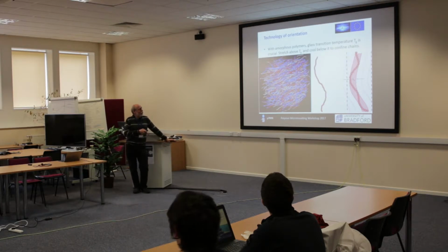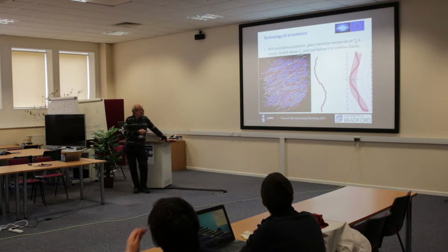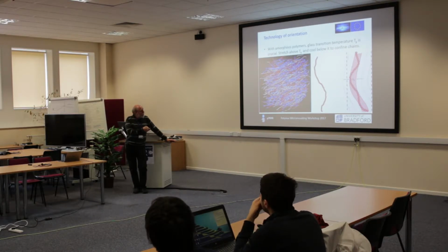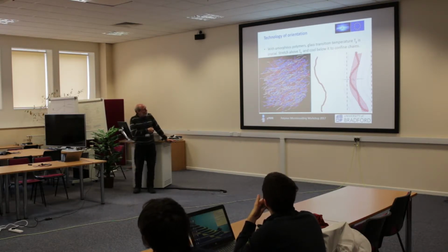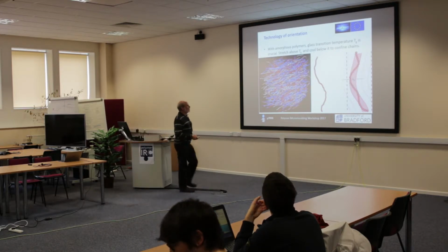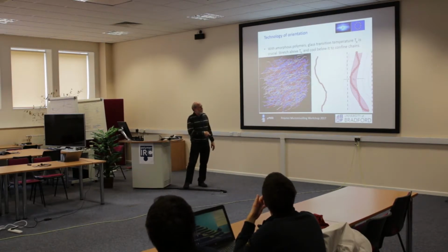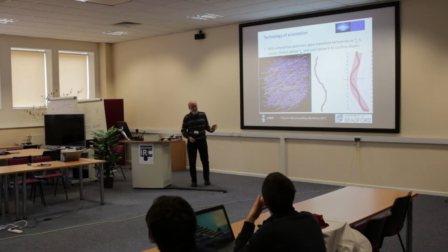The thing is controlled by the glass transition temperature. Below the glass transition temperature, the polymer chains are close together, interacting with each other, so you can't easily deform a polymer chain. You can't straighten it out because the other chains are getting in the way. So a polymer chain acts as if it's in a confining tube, because of the fields produced by the other molecules. So it's got a certain radius of gyration.